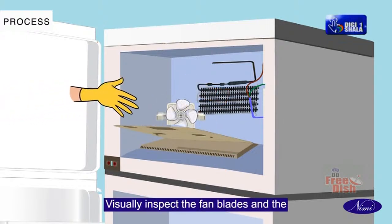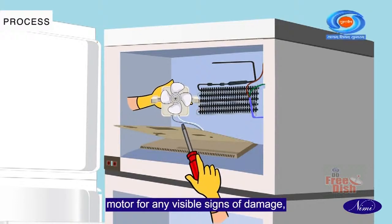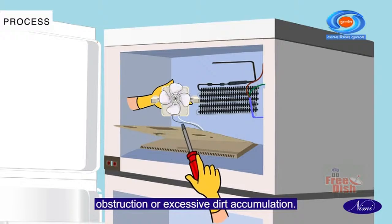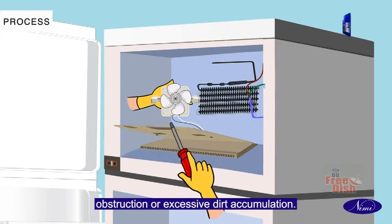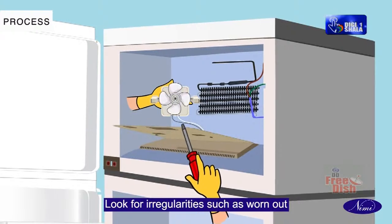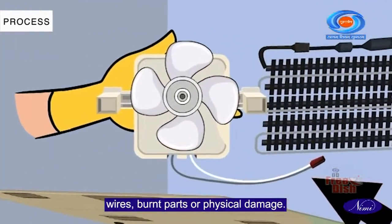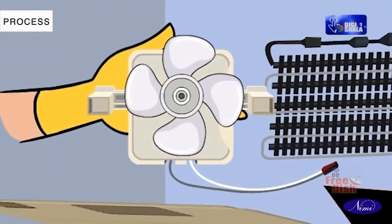Visually inspect the fan blades and the motor for any visible signs of damage, obstruction, or excessive dirt accumulation. Look for irregularities such as worn-out wires, burnt parts, or physical damage.